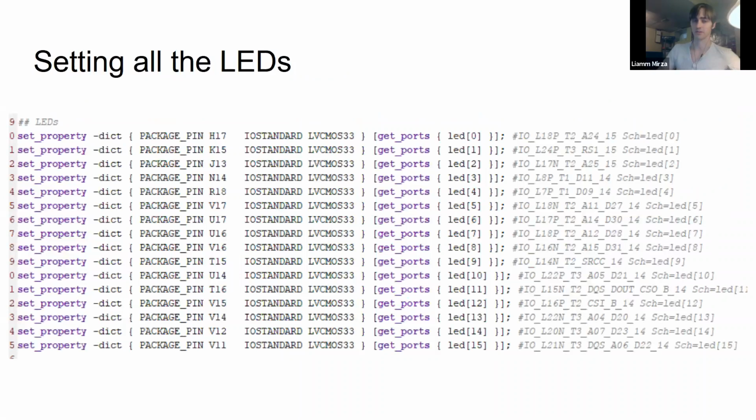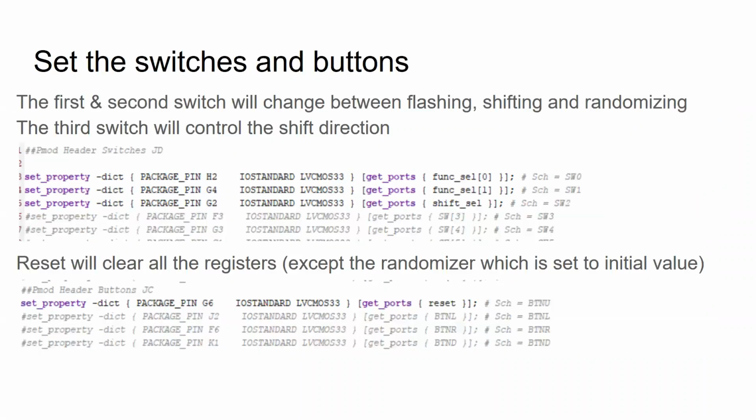And turning the FPGA totally on and off is a hard reset. Oh, I see. But typically in your Verilog designs, you still want to name it reset, even though it's not really a reset. I originally had an actual CPU reset pin, like another button, so the design used to be different. That would be the hard reset. But I ended up removing that because it overcomplicated things.